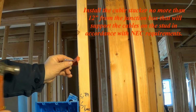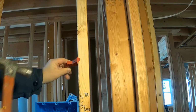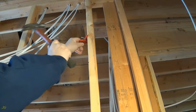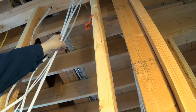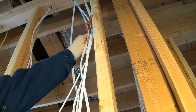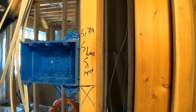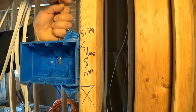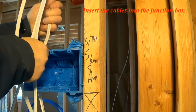Install the cable stacker no more than 12 inches from the junction box that will support the cables on the stud in accordance with NEC requirements. Insert the cables into the junction box.